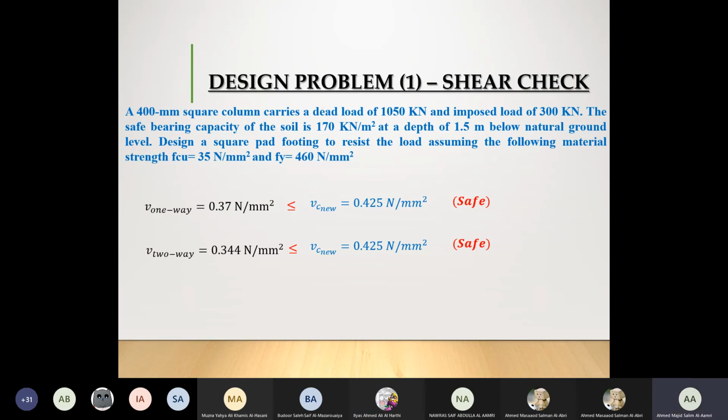Normally, when it comes to slabs, we prefer to avoid deflection. We normally prefer to increase the depth. Increasing the depth is cheaper than increasing the reinforcement, because my slab is a large area. So if you increase your reinforcement, you will be increasing it for a larger area.